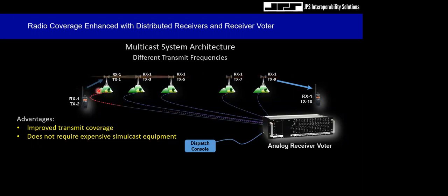All right. So some of you that are thinking ahead of me, you might be thinking, oh, this could be a problem, because once we start talking about transmitting multiple signals into the environment, we run into issues that can cause phase degradation, especially if I'm operating in an overlap region where I might be able to receive both transmit signals from these remote sites, and that will create interference in my subscriber unit.